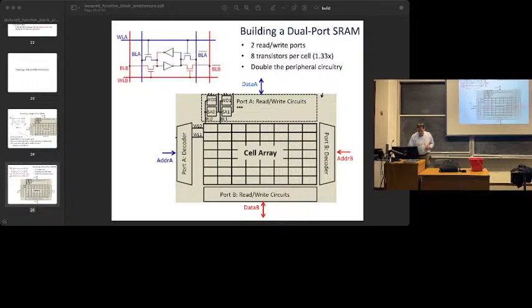I know Stratix 10, so a recent Intel FPGA, actually changed its RAM core so that it basically made a dedicated read port and a dedicated write port to make it easier to design it. So usually it's what I've shown you here, which is a true read-write core, where you have 2 ports that can do either. But there's at least one FPGA that didn't do that in order to make the RAM design easier. Does that make sense?